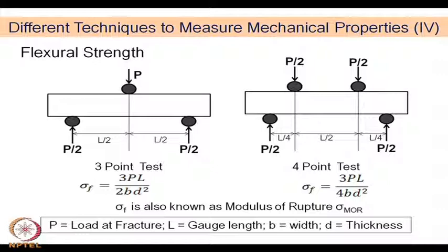Flexural strength is of course very common in brittle solids. It is not so important in ductile materials. So, metals and alloys do not perform this kind of test so much. Metallurgists will perform tensile tests, whereas ceramists will perform flexural strength or compressive strength tests.